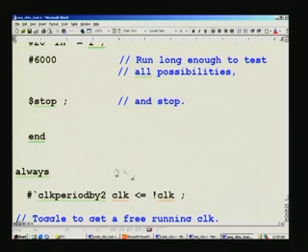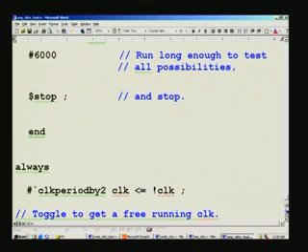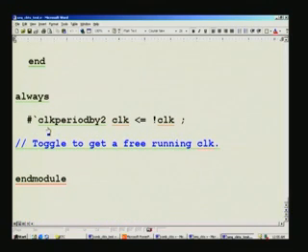So, now comes your question, which will be answered in one statement, as I said. See, we said after clock period by 2, this was equated to 10 there, which implies 10 nanosecond. That means you take this decision only every 10 nanoseconds afterwards. So, this means I said that all the statements are concurrent as well, right. So, this is an always block, a separate block as such.